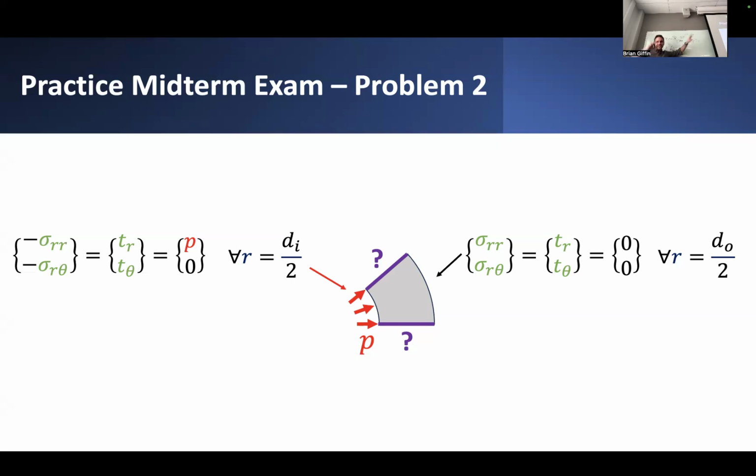And you can use this just to do a sanity check. What this means is that if n is pointed outwards, if n has components 1 in the radial direction and 0 in the tangential direction, then we're looking at components of stress on this outward face. But if n points inward, so -1 in the radial direction and 0 in the tangential direction, then we get negative values for these components, giving us what the traction should be.